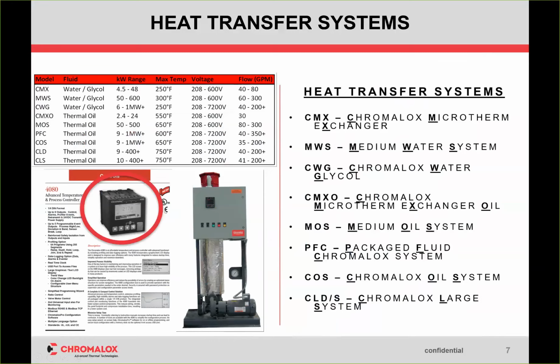In which case, the 4080, and you probably saw the letter from marketing last week, even our CMXOs are now going to incorporate the 4080, which will control the cooling loop as well. It'll do both open and closed loop cooling, but for the larger systems, open loop cooling is really not an option. We're using heat transfer fluid and higher temperatures, and I can't even think of an application where you would not have a closed loop cooling for anything outside of water. Hopefully that is a better explanation. I'll give you a chance to ask any more questions before I begin.